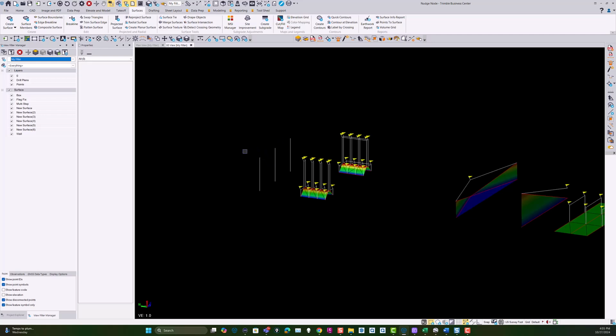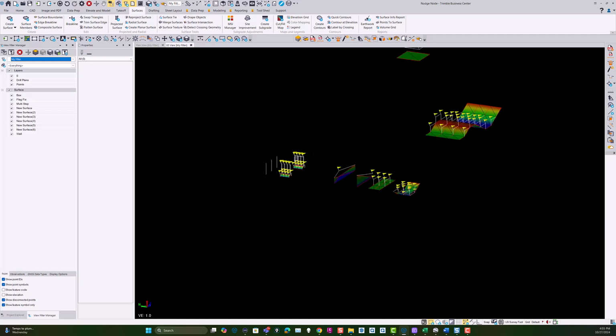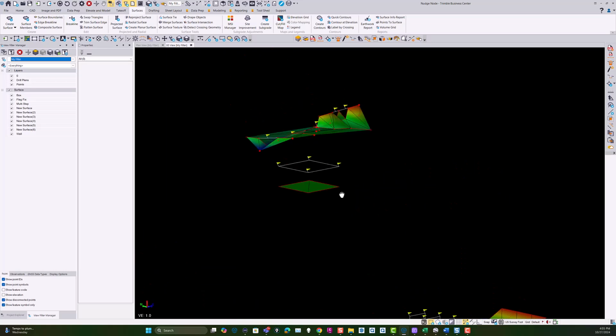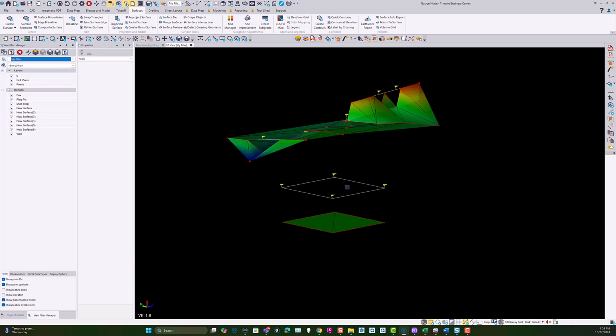So in this case you need to nudge one of the nodes out of the top or the bottom in a specific direction to take them off vertical so a surface can actually form. These are just more examples of the same thing. Up here, this is fairly typical of a basement or a subgrade adjustment, and you end up with a top and a bottom where it's meant to be a box out, or it's meant to be a vertical upstand, and one of the two, you're getting two lines in the same place vertically separated, and again you get flags.